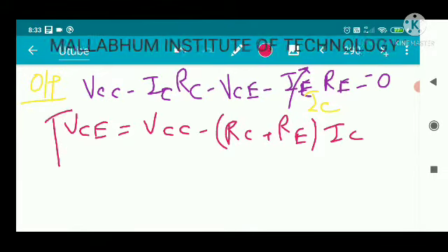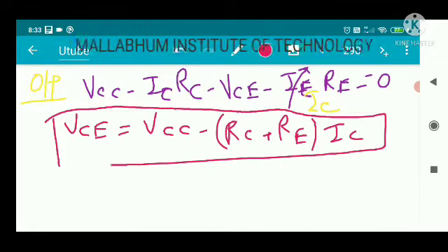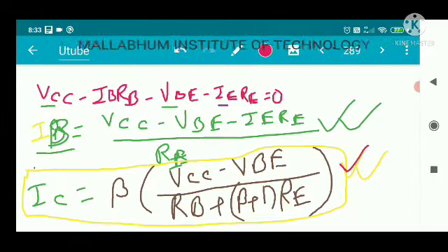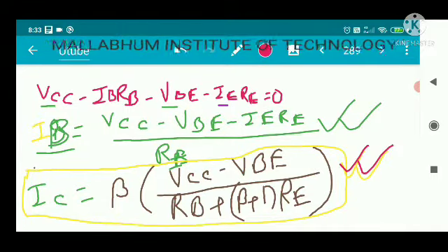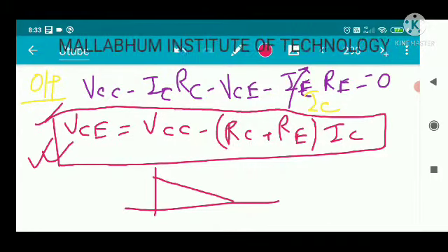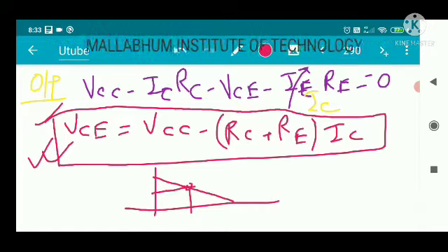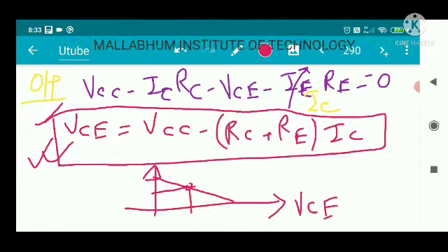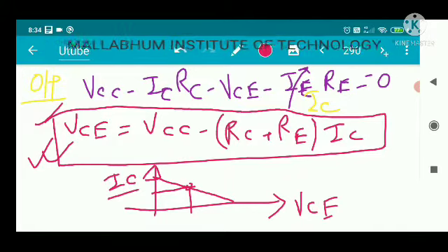Okay, so this is another voltage that will be required for the calculation of the Q point. Through the Q point value we will get IC and VC. So in the load line we will just get the Q point, just IC and VC. This is the IC and this is the VC that we require for every biasing configuration. We want to calculate these two values.